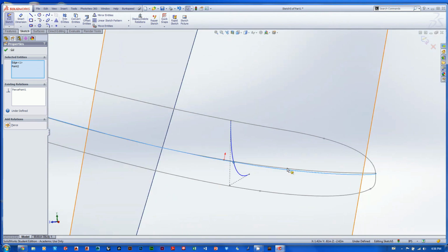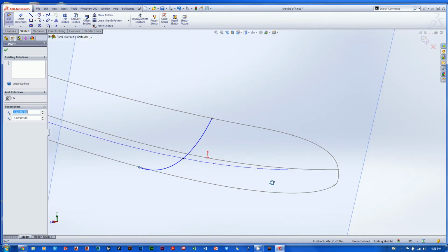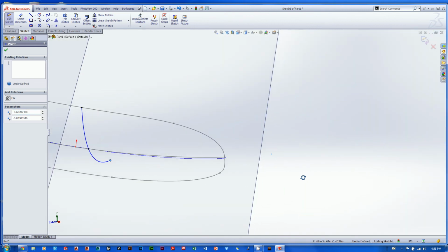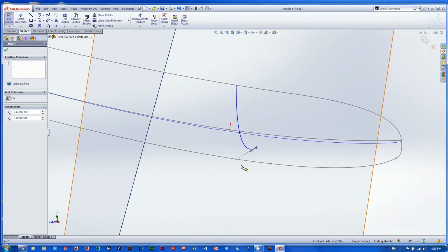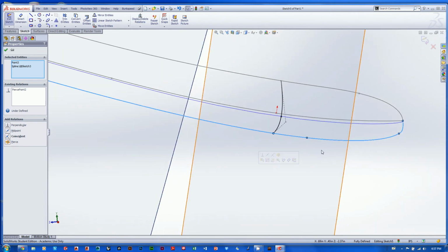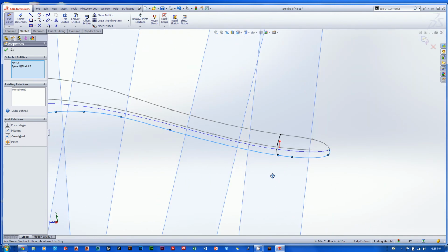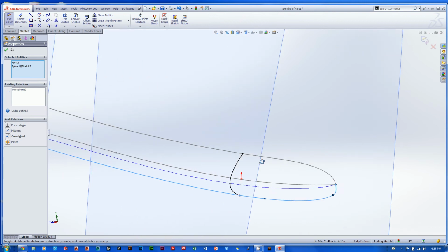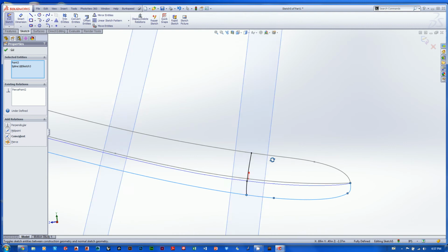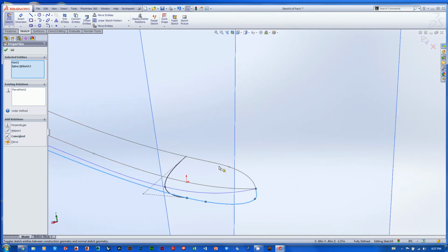So the last thing to do is to take this end point of the line, and attach it to this bottom profile curve. Now it's thrown way out there in space, but using our make pierce command, holding down Control with a right click, make pierce, it just pops it right into place. Excuse me while I orient myself. And you can see what we've done now. We've now attached that line that was previously way out in the middle of nowhere, and it now attaches to the top, center line and bottom profile of our curve.